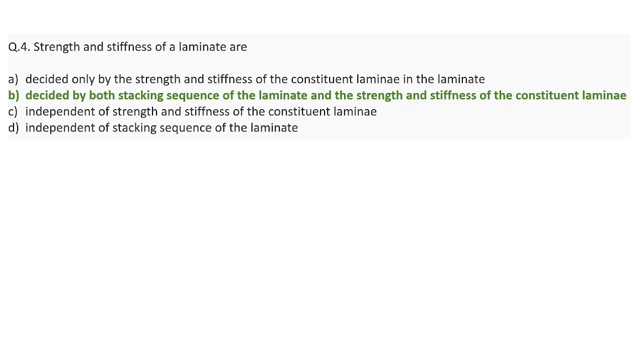Hence, the stacking sequence is also very important. Hence, the answer will be that the strength and stiffness of the laminate is decided by both the stacking sequence of the laminate and the strength and stiffness of the constituent laminae.